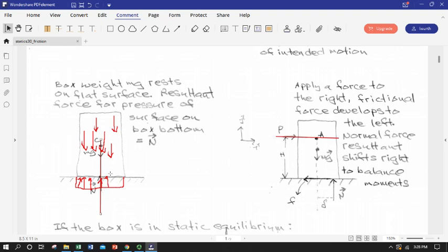Okay, so when we're looking at weight, and especially when we're looking at normal force, just keep in the back of your mind, this is a force resultant that's representing the action of a distributed load, which may or may not be uniform. And that's effectively what we're going to find over here, that in this case, over on the static side, the left side, or no horizontal force side, excuse me, our normal force was uniform.